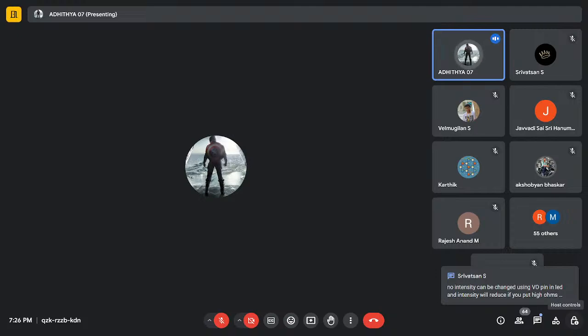I'll be showing the simulation now. Here I have selected it, and as you can see, it shows 123 centimeters here, and it's 123 centimeters here. As soon as I change it, it will change. That 500 is why every 500 milliseconds it is changing. If I change that 500 milliseconds to, say, 1 second, every 1 second it will check the value. So it's more or less like a sampling rate. Sampling rate is how often you check the value.